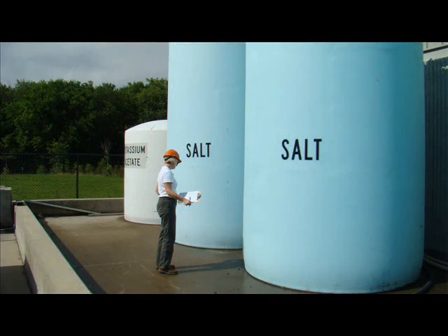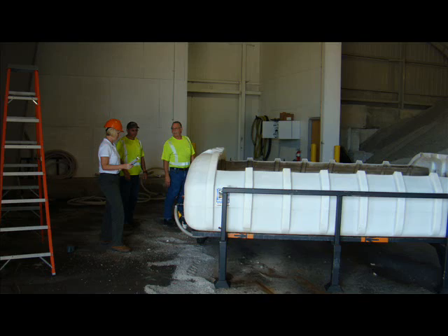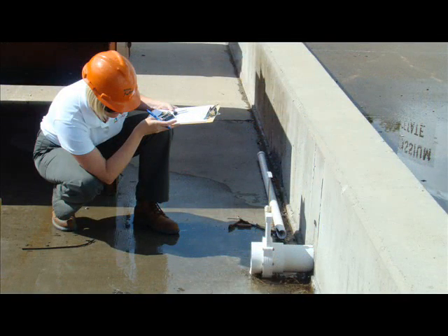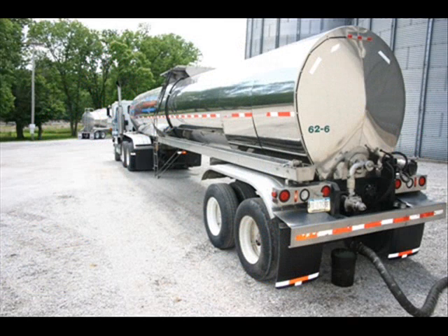For salt storage, look for secondary containment for brine containers, names on each container, leaks, stains, and closed drainage valves, except when draining stormwater. Transfer areas should be on impervious surfaces that don't drain to storm sewers or drainage ways.